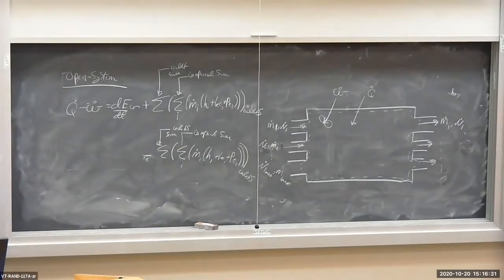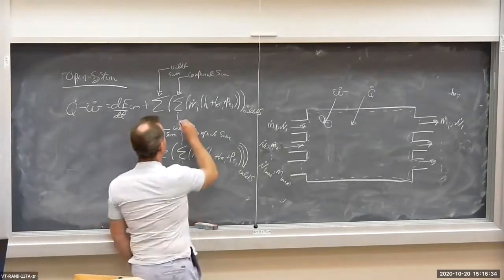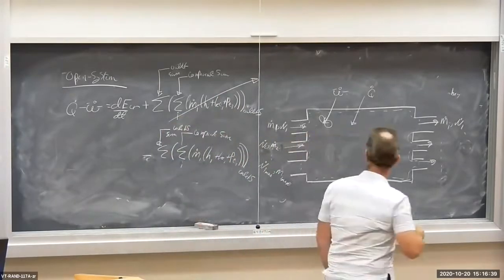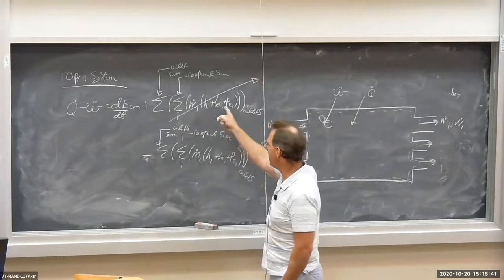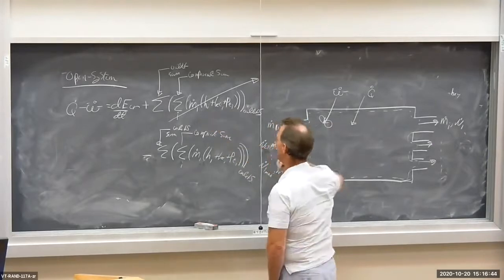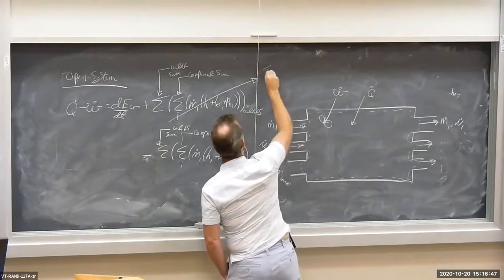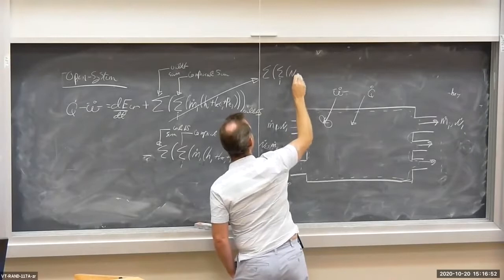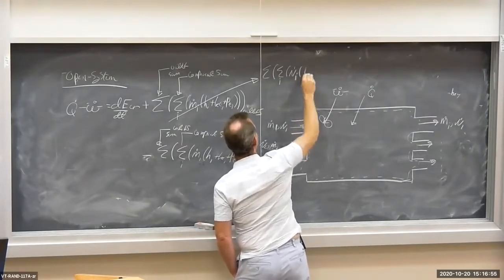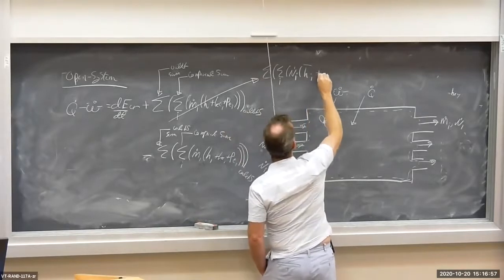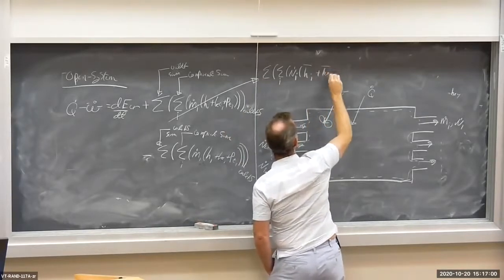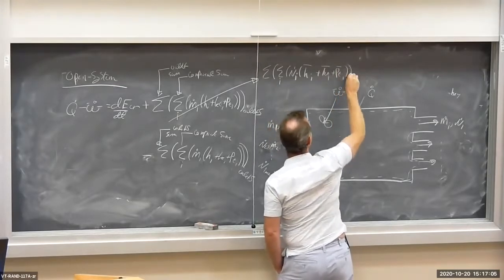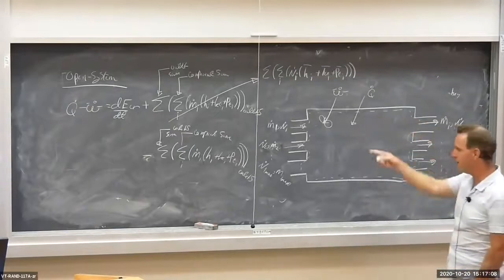Now you can also write this in terms of mole flow rates. I can use H bar, KE bar, PE bar, and N dot there. I can also do this: sum over all outlets, sum over all components, N dot I, H bar I plus KE bar I plus PE bar I. Same thing with the inlet term.